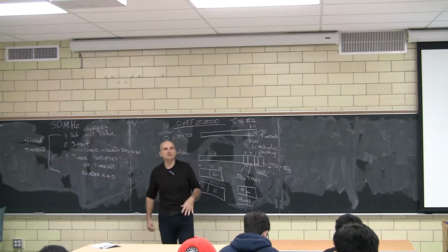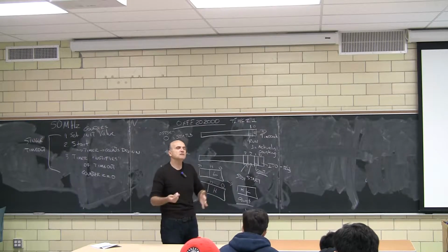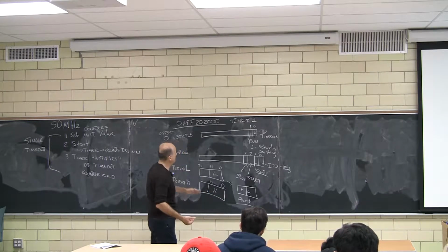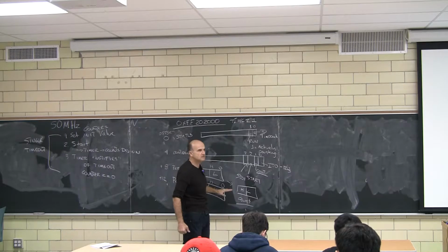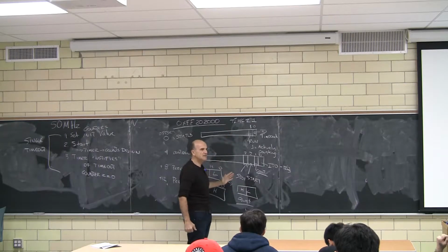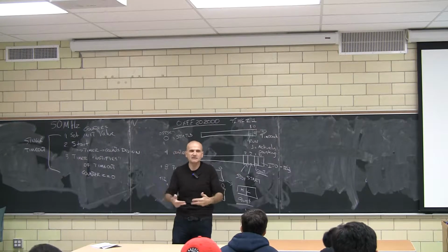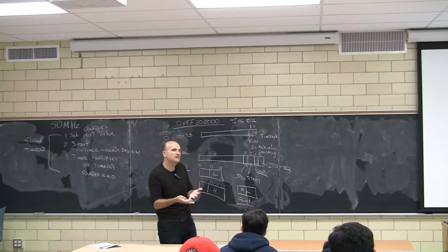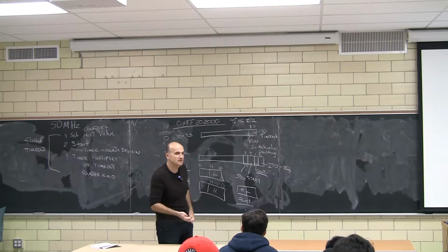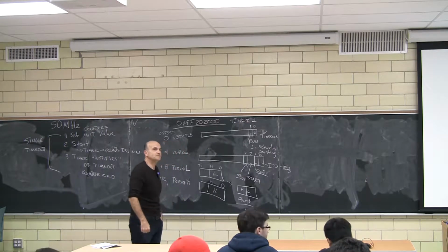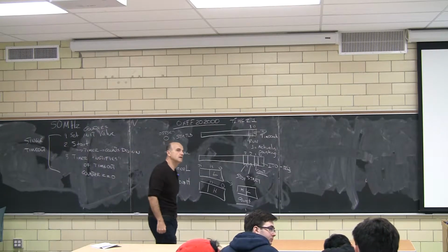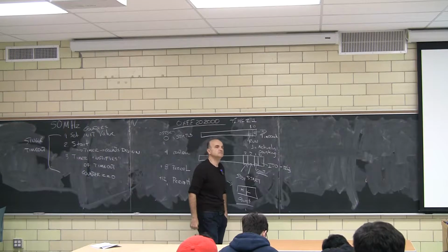Now, if you care why this is done, it's because it simplifies the hardware underneath. Even though these registers are 32 bits, we only use values that are relevant to us in the lower 16 bits. So it turns out that when you actually build this thing, it is much easier to build the hardware to connect these two. That's what is behind it. And when you put them together, what is this supposed to represent? A 32-bit number.